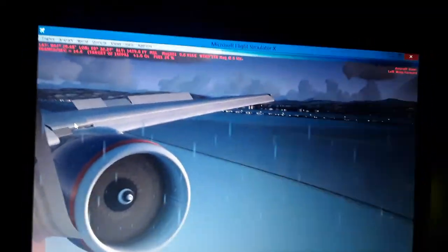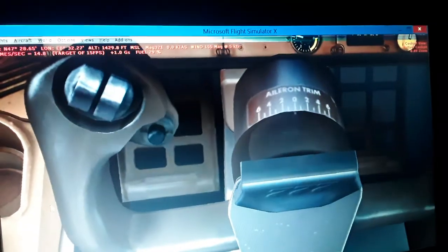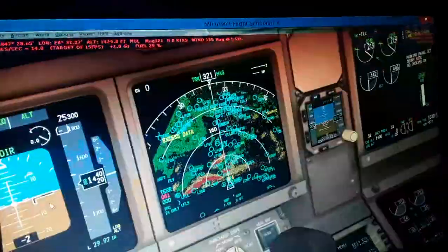Right now I'm gonna show you a little bit more inside. You can see again here we have a proportional movement. So I'm gonna show you also some more things about the aircraft now. You can see the horizontal, this is a secondary flight control, the horizontal tail position. I told you you can use this switch here to position up and down the horizontal tail trim.